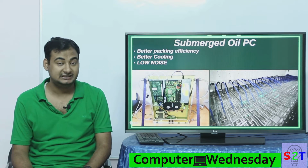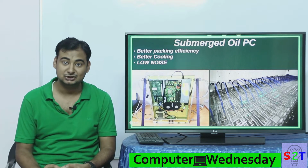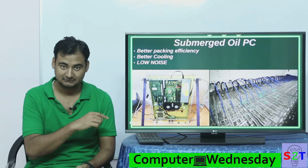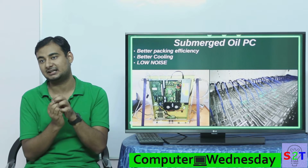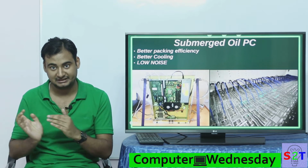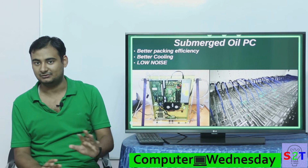Now oil has many advantages. First, it's fully submerged, so there is no humidity touching your components. Humidity does cause your components to fail prematurely because of corrosion. Benefit number one. Second, because it's fully submerged, there is no hot spot. There is no spot where, let's say, your CPU got too hot and it started to bend the motherboard, like in PlayStation, and it does happen in servers. It's not too often, they generally design it well, but things like that happen. Here, no worry about that.